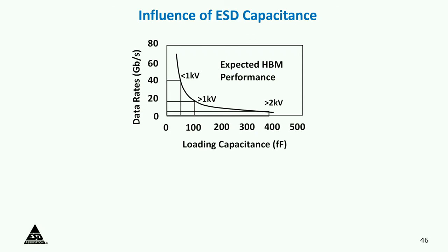I didn't mention to you about RF. RF is even worse. RF is so sensitive to noise gain, so any small ESD diode can really disrupt the RF performance of these devices. So then what you do is what is called a design space. You work with an RF designer and ESD designer together, saying, I put an inductor, I put a clamp on this side of it, it will not degrade the RF performance and still give me a minimum protection.